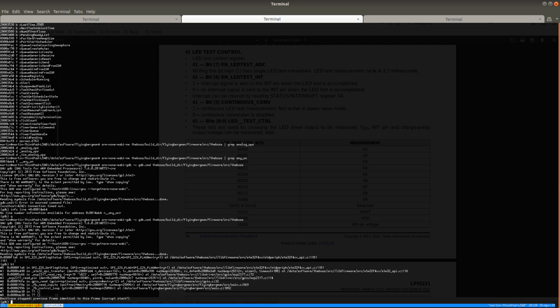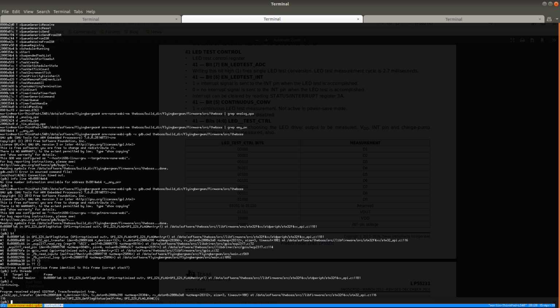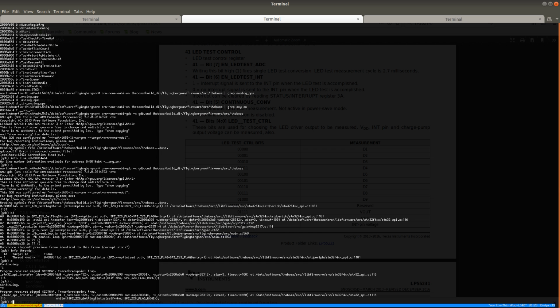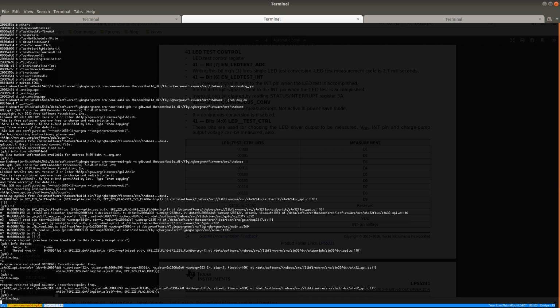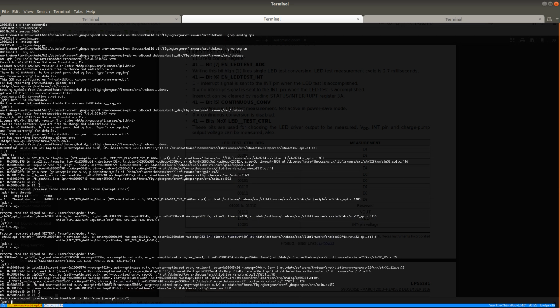This is one of the things that I find a little bit cumbersome to do in GDB. It's kind of not aware of FreeRTOS threads. Let's see. Where did it crash? Oh, yeah. Let's see. So read register, and I'm reading reg 58. And I'm waiting for